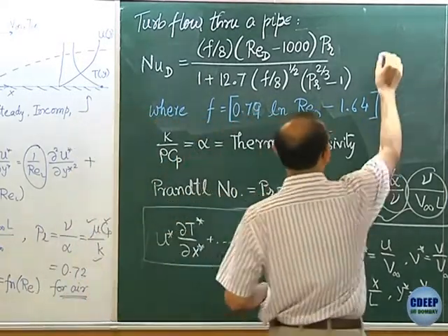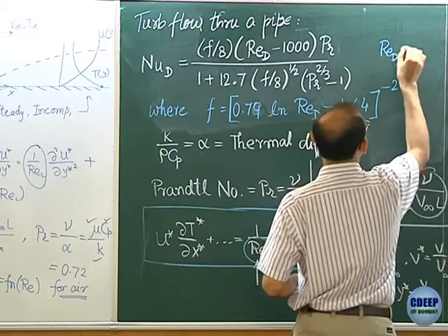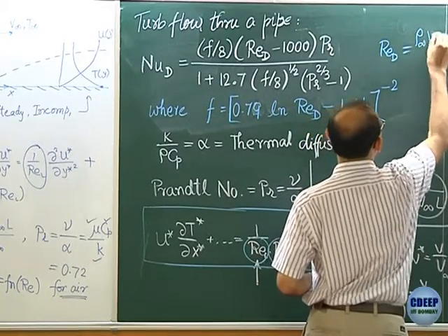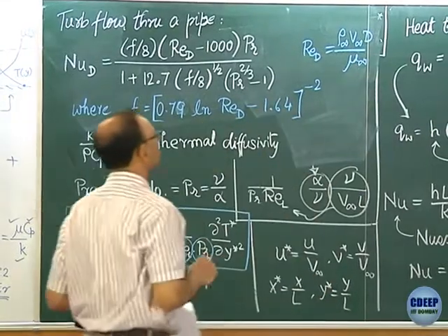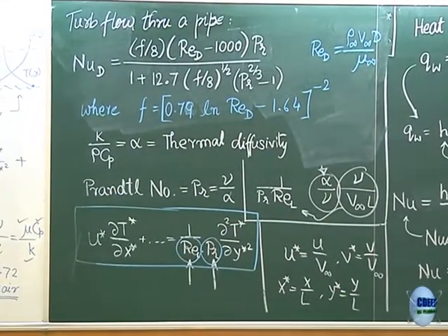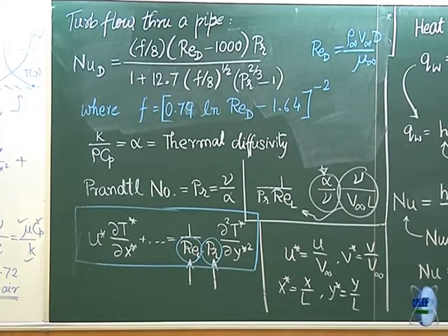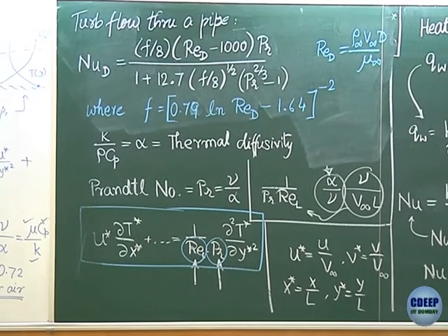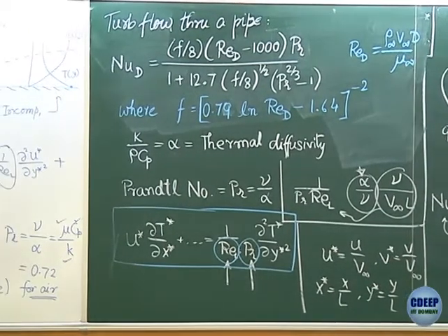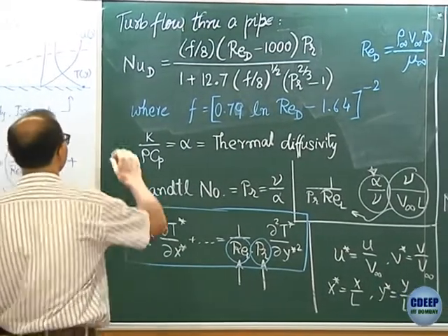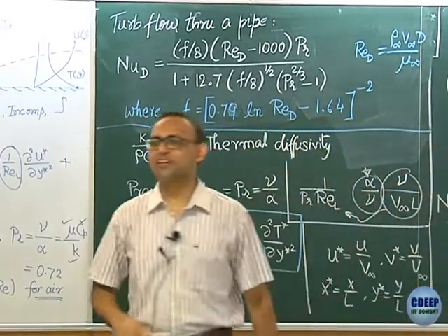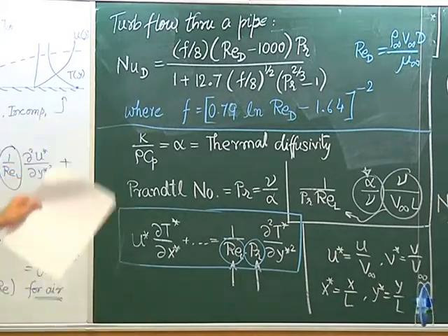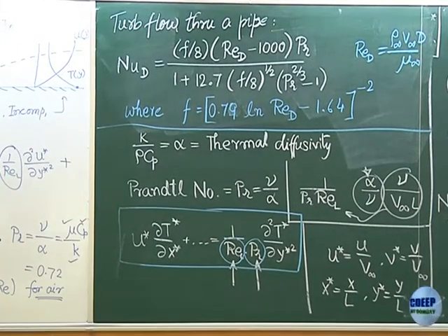And Re, Reynolds number based on diameter, is probably, you can guess, a flat plate, a pipe still have the simplest geometries for which we have these expressions. All are experimental, except for the laminar boundary layer. Much of these are based on experimental data.